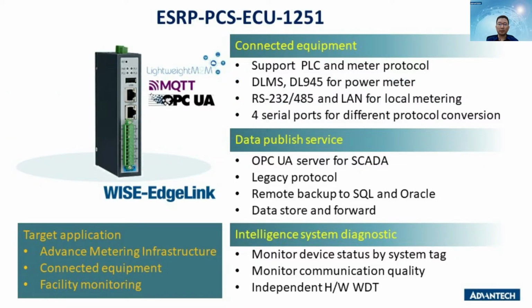Okay, next, we would like to introduce ECU 1251 bundled with WISE-EdgeLink. The product number is shown above the slide. This device supports PLC and meter protocol, supporting DLMS and DL945 for power meter, having RS-232 or 485 and LAN ports, with 4 serial ports for different protocol conversions.